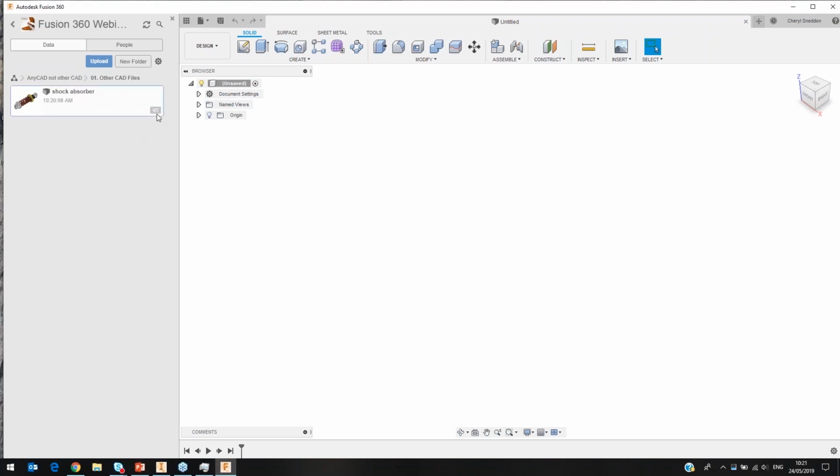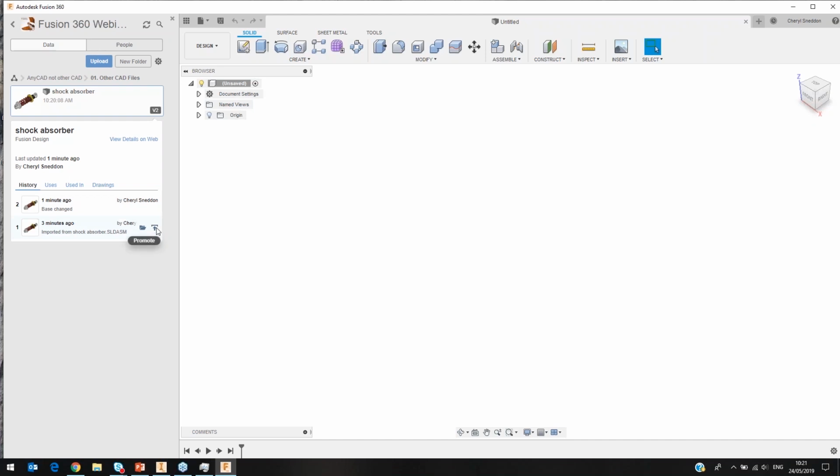So like I say, we've got 2 versions of this file now, guys. What we can do here, if you look under the information history, is you've got a button to click on promote. At the moment you can actually open multiple versions, though it's maybe not recommended. Don't open multiple versions because you might get a bit confused, but you can promote back to the previous version, which is a very nice tool within Fusion.